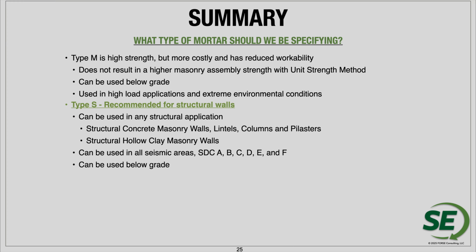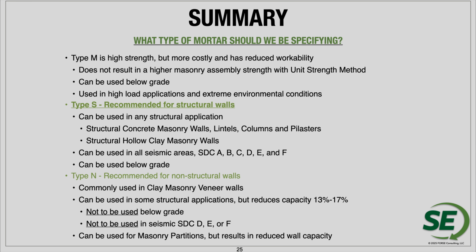It's just really hard to work with, hard to clean. It's just not an easy mortar for them to work with. They would strongly prefer to use type S. We also have type N, which is also available, and it's going to be the weaker of the three.